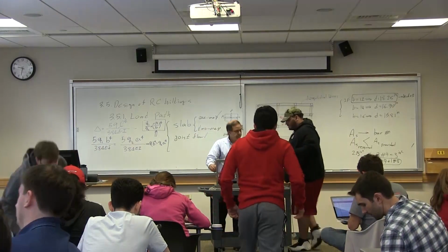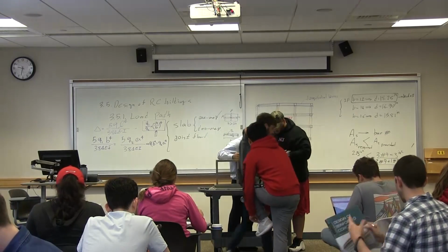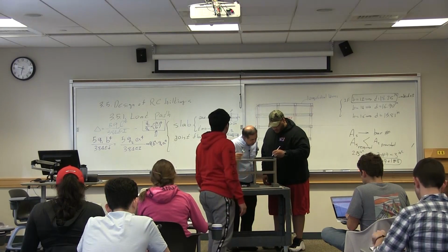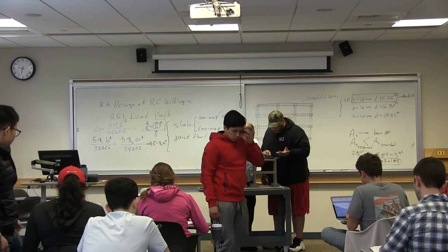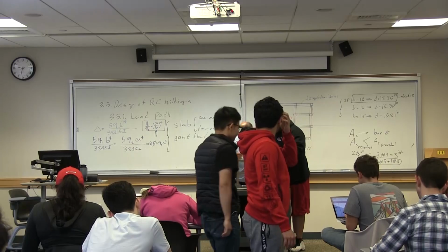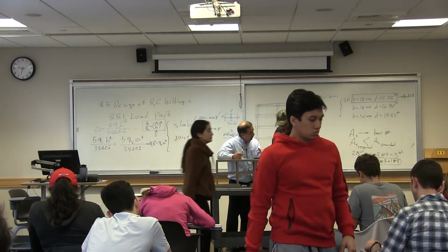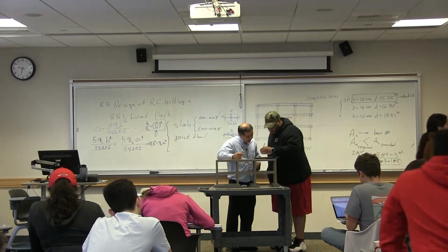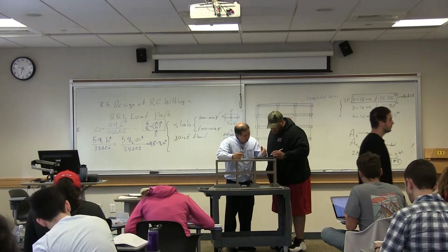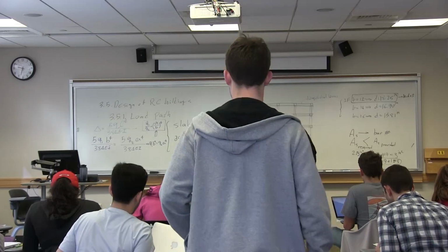I didn't hear that. I missed some of the lecture. So you were, okay. I understand the compatibility equations. That's how we're getting this. What does this ratio mean? The Q1 to Q2 is how much load is transferred in one direction to the other direction. Q1 is load transferred in one direction, Q2 is load transferred in the other direction. Let's say this is the slab and you go and stand on top of it.